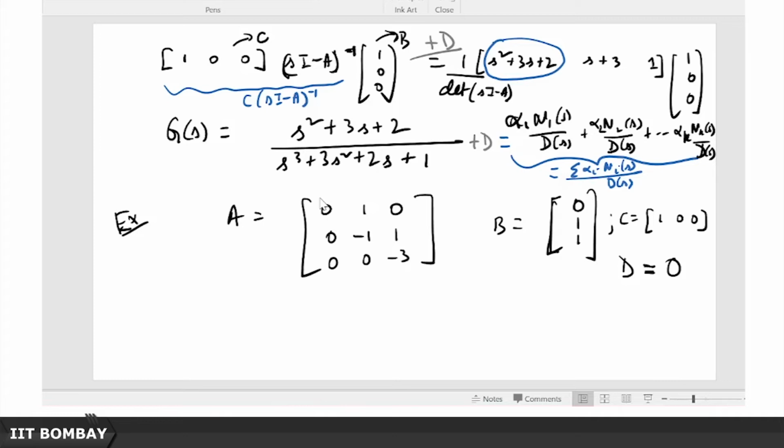And because much of modern control theory has to do with state space and we like state space realizable controllers, all our problems are formulated as controllers given in their state space form. So the plant is given in its state space form, just like in the earlier case in the classical method we had G(s) and C(s), right. So G(s) was a transfer function, C(s) was a transfer function. Here in modern control theory, in the general case, we have the plant given as a state space realization and the controller that we want to design must also have a state space realization.